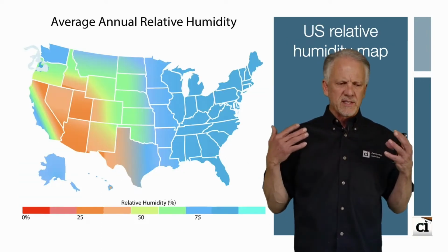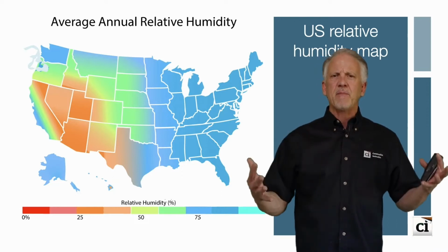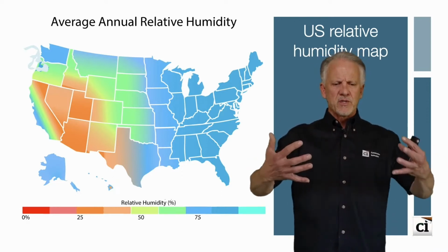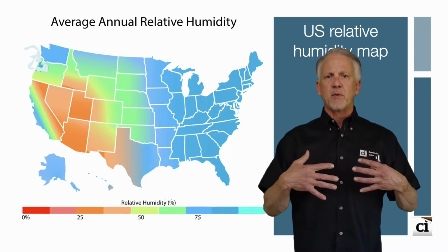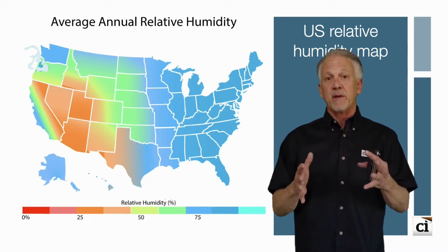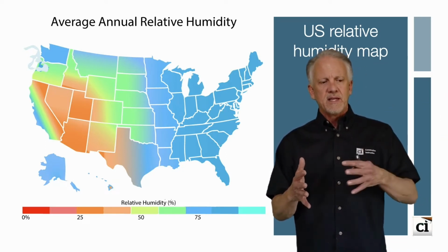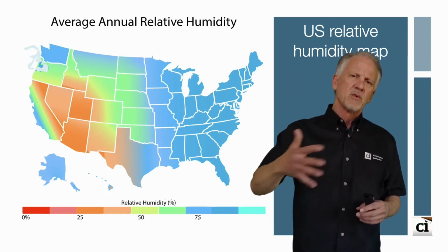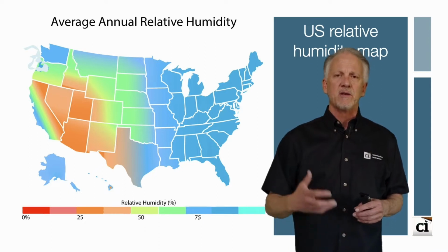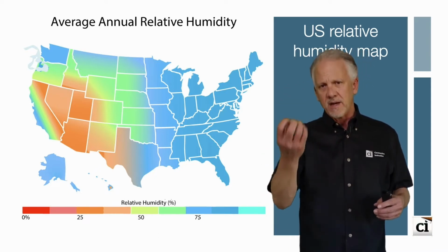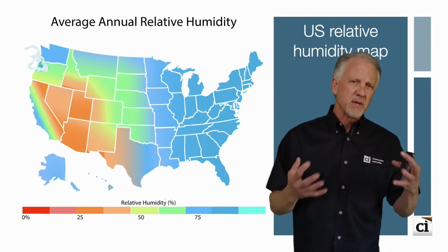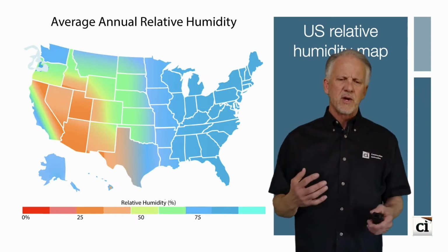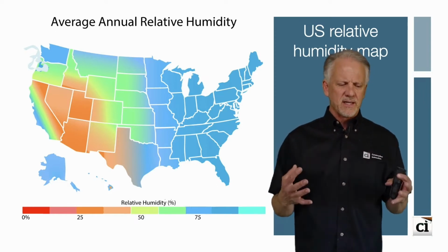We can also look at things like relative humidity and how that behaves. How are climates where the moisture levels are elevated, both on the cladding type as well as the inability for it to dry back to the outdoors? If the outdoors has a very high dew point, very high relative humidity, oftentimes we'll see that it gets driven back to the inside where it's being air conditioned and dehumidified. So there's a lot of complexities going on here. So what we want to do is try to ensure that our systems are designed correctly.